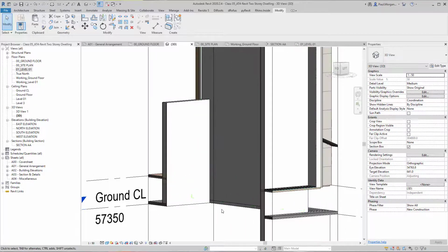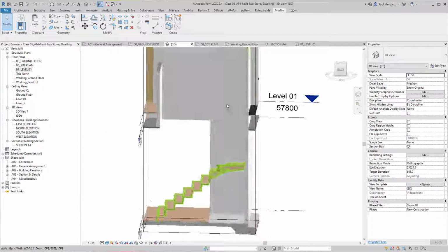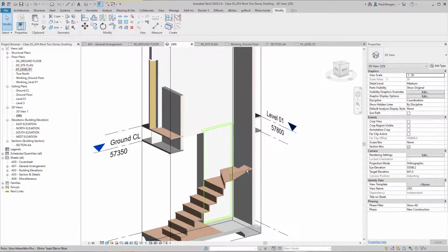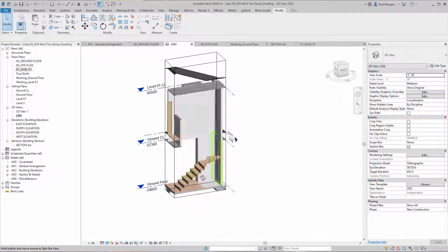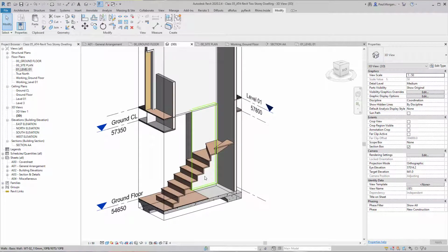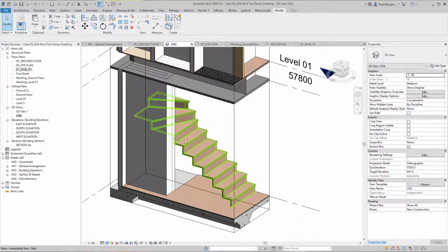Like that looks much better now, that sort of balustrade wall. But that needs to be cleaned up. And it's very typical that this does happen. And you won't see it till you start doing stuff like this with section boxing in 3D. But again, it's just something to look out for, and some of the methodologies and workflows you can use to clean that up. The last thing I'm going to do is just do a wall here that will end up being like a balustrade.